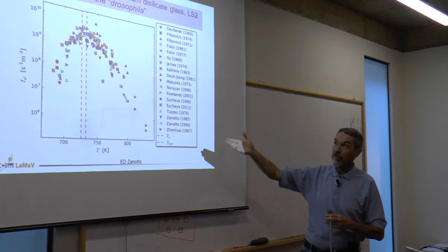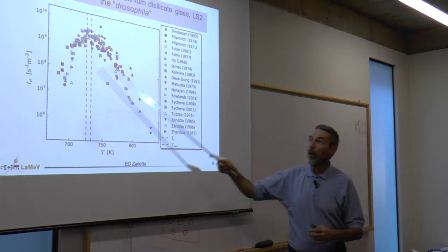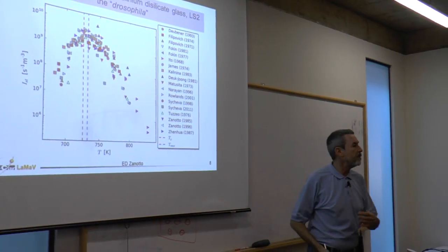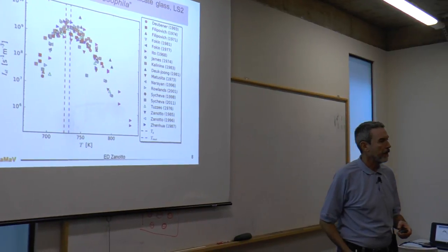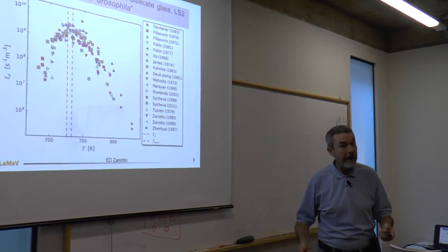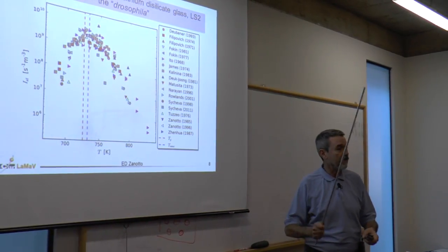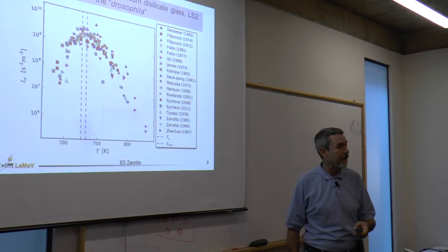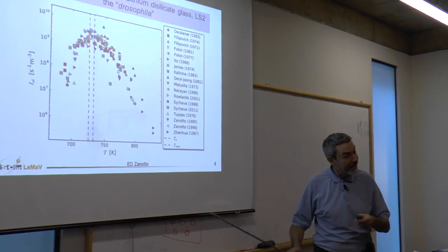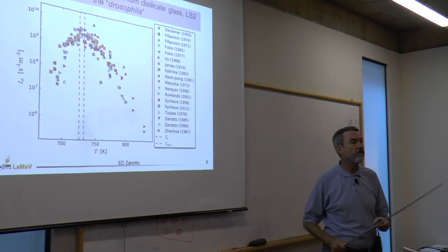But if you estimate the surface energies from all these nucleation rate curves, you see that they're about the same. This is a strong indication of homogeneous nucleation, despite the fact that not many people believe that homogeneous nucleation can take place. But in glasses, it can, because glasses are universal solvents.